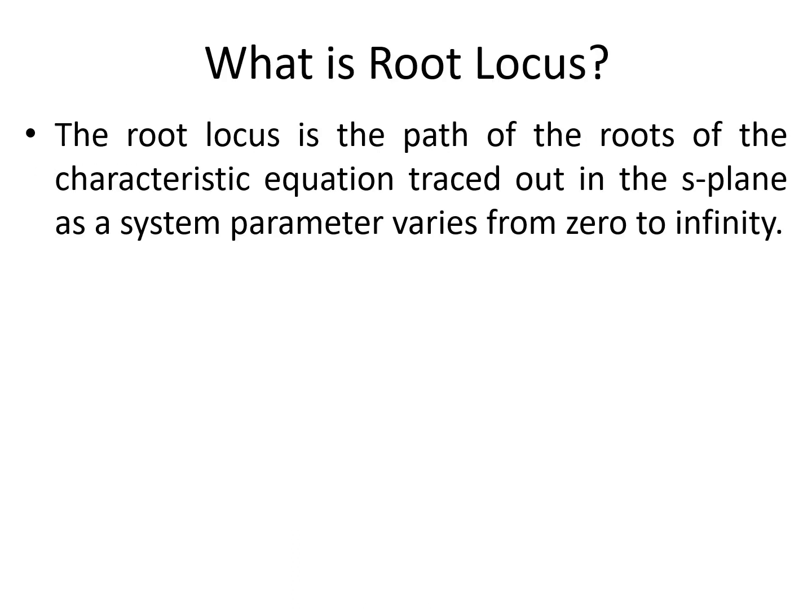So the root locus is actually based on this concept only. We are defining the root locus. The root locus is the path of the roots of the characteristic equation traced out in the S-plane, as the system parameter like k varies from 0 to infinity. That was shown in the last slide. You could see how the location of the poles varies when we change the value of k from 0 to different values till up to infinity. So that is the definition of a root locus.